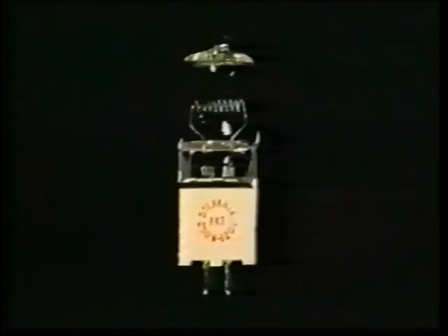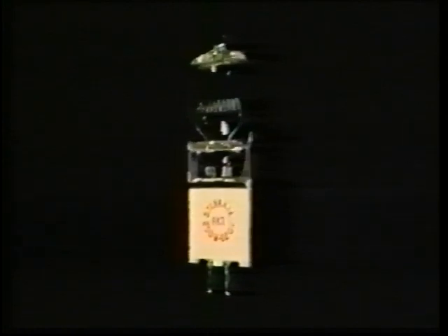It's appropriate that we now discuss the most advanced incandescent lamp of all, the tungsten halogen lamp. As an incandescent lamp ages, the heat of the filament causes tungsten atoms to evaporate. The tungsten atoms deposit themselves on the bulb wall, which is much colder than the filament. When enough tungsten has evaporated and the filament becomes too thin, the tungsten wire breaks and the lamp fails.